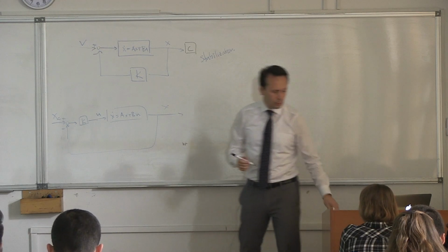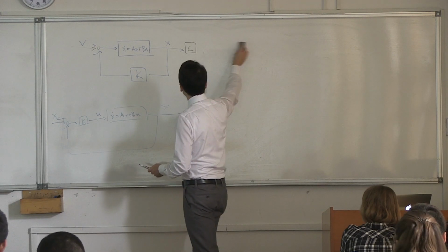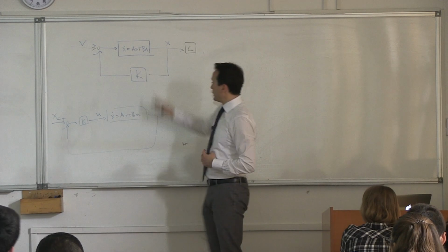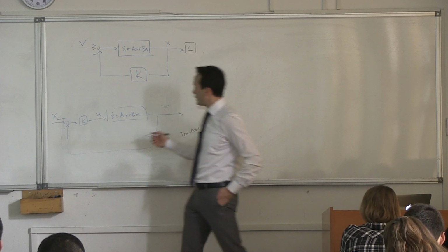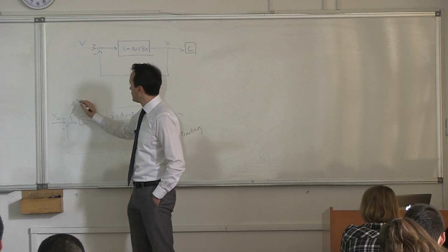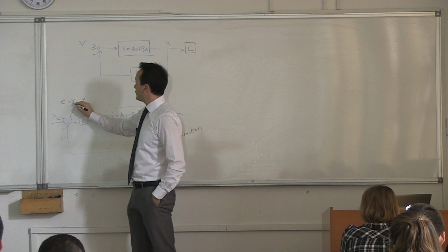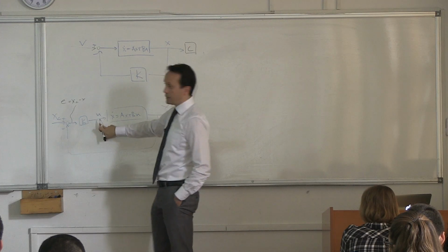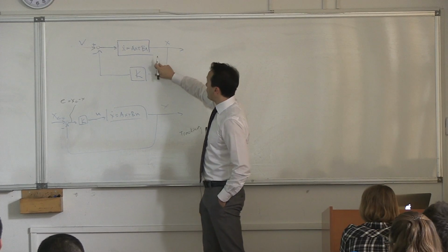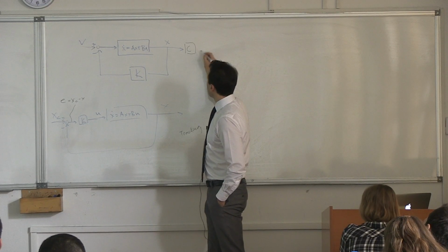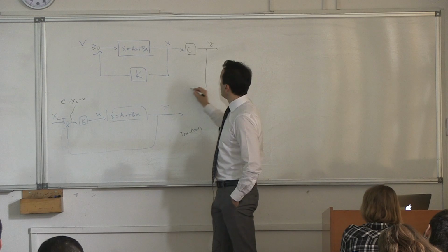around the stabilization loop, to track something, to track a variable, okay? So this is the stabilization, and this would be some sort of a tracking problem. The reason I'm calling this a tracking problem is this signal over here is xc minus x, so it's kind of the error, right? So you're trying to reduce the error. If there's an error, you multiply it with k and send it over here. But this is not always possible, so what you would do is you would simply take one of those variables and wrap another loop around this,